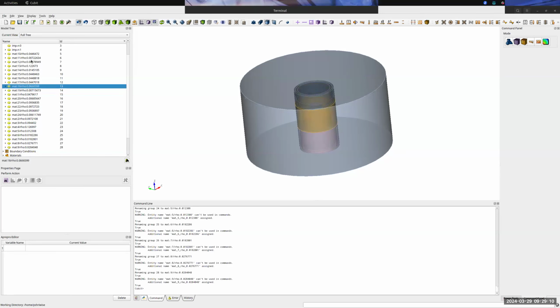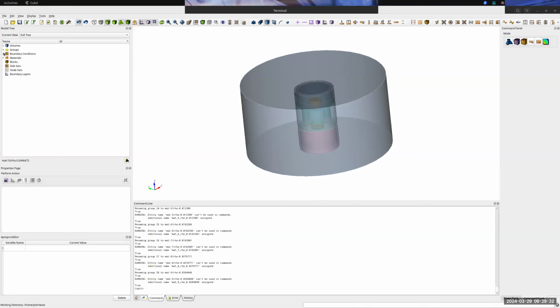And so at this point, we could use the old DAGMC workflow and exporter to leverage these group names, but in the Coreform integrated DAGMC space, we're trying to use constructs that are more relevant or more purpose-built for these kinds of material assignment operations. And so, as we talked about a lot in the previous webinar, we are really trying to move to things where we're using mesh-based constructs within the GUI, within the Coreform model, so that we don't have to worry about things like exporting and importing and losing this metadata.